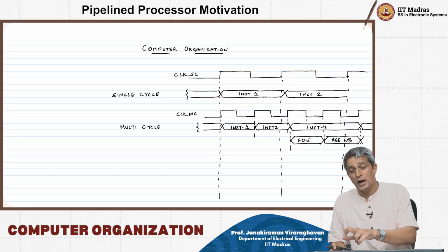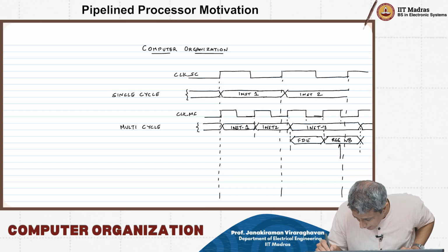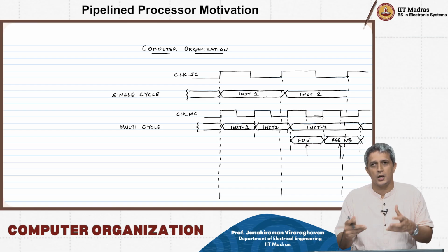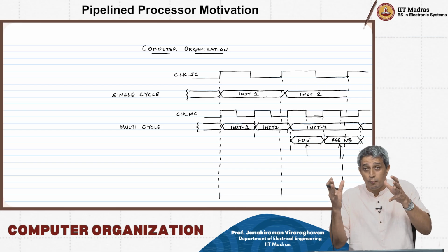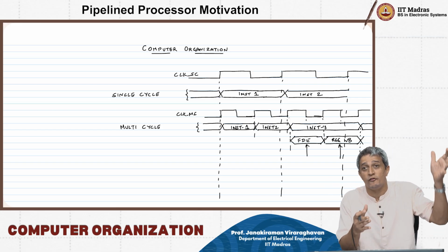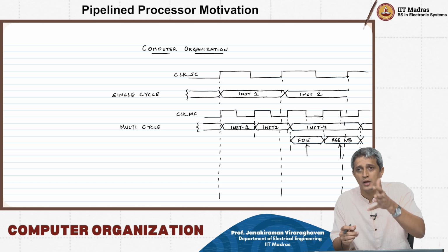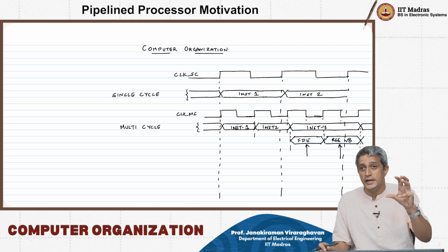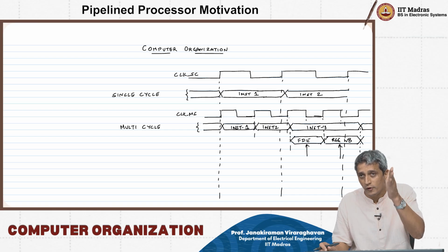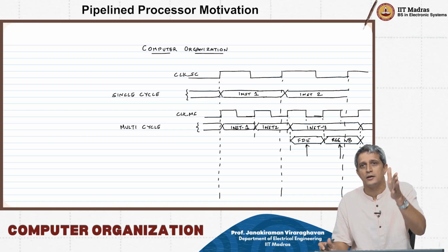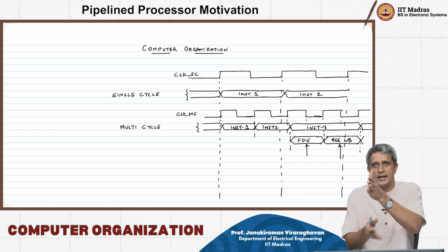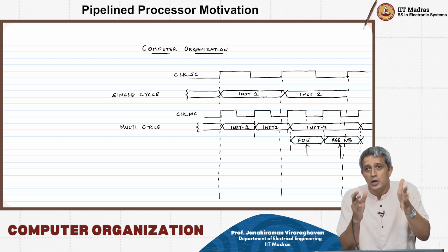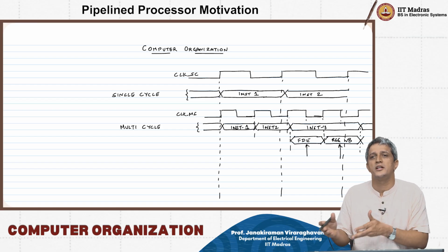Okay, but while this register write back phase is happening, the part of the circuit which did the fetch, decode and execute is technically doing nothing, though it can be used because there is a flip flop for you to hold the data at the point where register write back has to happen. The previous stage is still doing nothing and it is waiting for this instruction to complete.